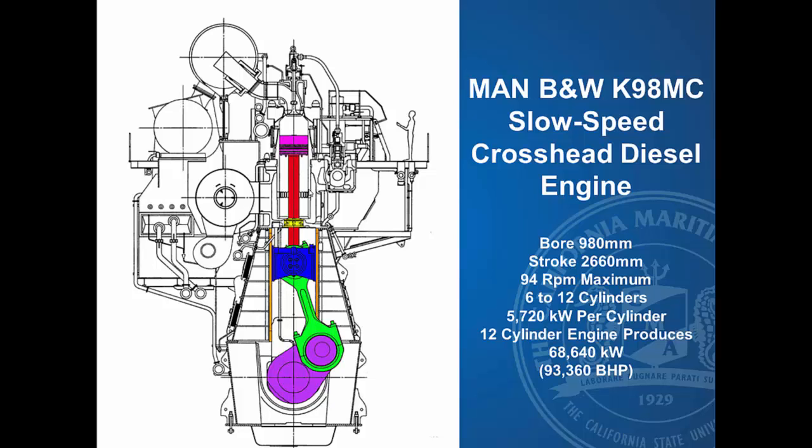And I've talked to some of their representatives about this, and the basic gist of what I received back is that since the pump is so large and the pipe is so short, these act more like a unit injector, and that the delivery valve was not a very high necessity for this pump.